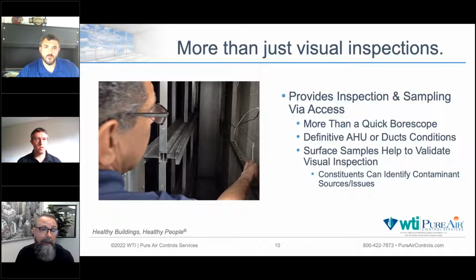So we're really deep diving into these units, both from a hygiene or cleanliness standpoint and a performance standpoint as well. And again, I'll mention that ASHRAE 62.1 in Section 8 covers an operations and maintenance manual for this type of equipment and does more than recommend. I mean, it basically outlines the plan to look at over 27 components inside of this mechanical equipment and on a regular cadence, sometimes maybe once a year, sometimes once a quarter. So again, if you're not familiar with that standard, you would want to brush up on it, and certainly these types of assessments and deep diving into them are going to help really meet those guidelines.